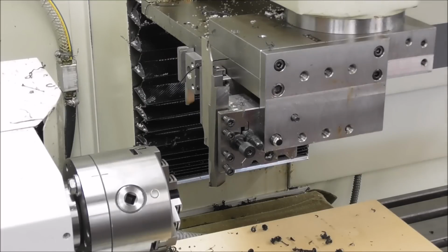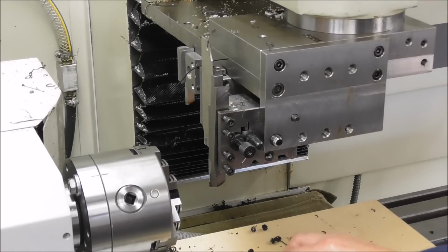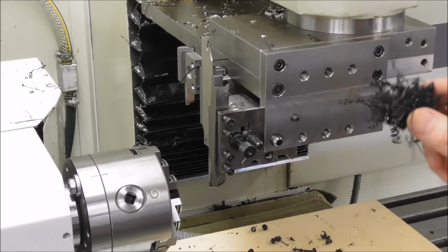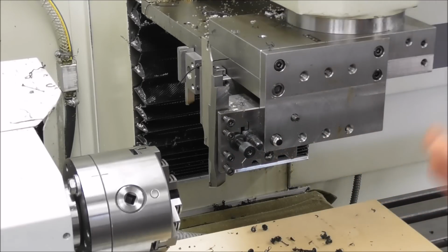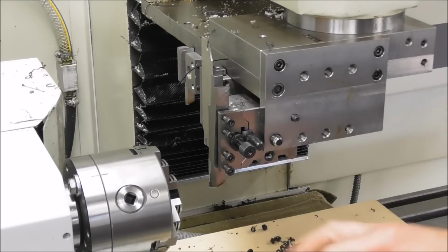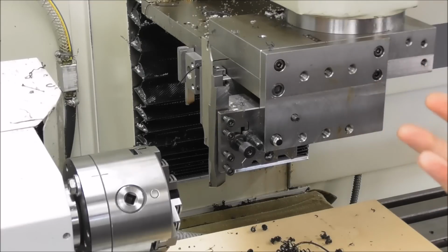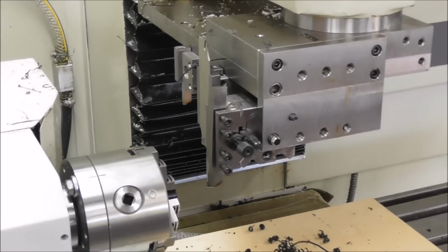And so you see, you can just slow down and speed up. It doesn't hurt PathPilot or Rapidturn, and you won't lose your position. And just go at a speed that you're comfortable with. Now, once you've run it once, that's the great thing about NC lathes. It'll just keep repeating itself. It's not going to do anything haywire again. As long as the first part's fine, you're going to be okay.